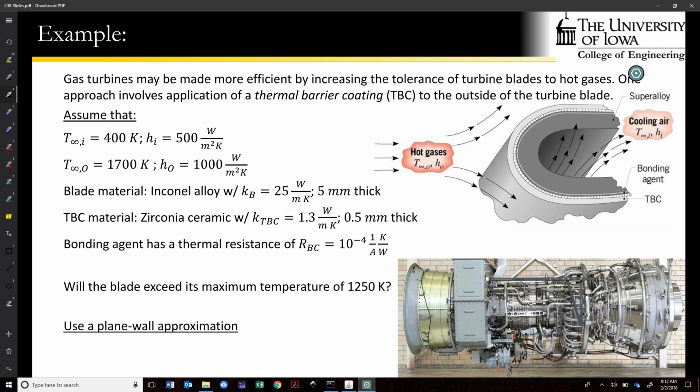So the idea is that these things generate and extract huge amounts of thermal energy, and they do so by combusting fuel and air mixtures, in the Brayton cycle, to form really high temperatures, and blowing that through multi-stage turbines, which extract essentially the pressure energy of that air flowing through and turn it into mechanical work.